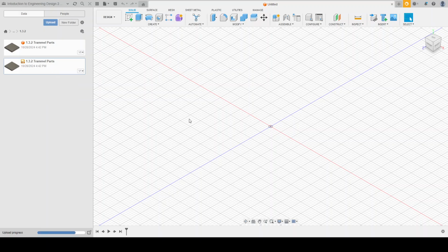And hit Create Fusion Design. It's going to start uploading it, and you can see the bar down at the bottom left as well. As that bar is uploading, you just kind of gotta wait and hang out. We can close this in the meantime. Then in the top left, it says it has been updated, so we can refresh, and now that new part is there.